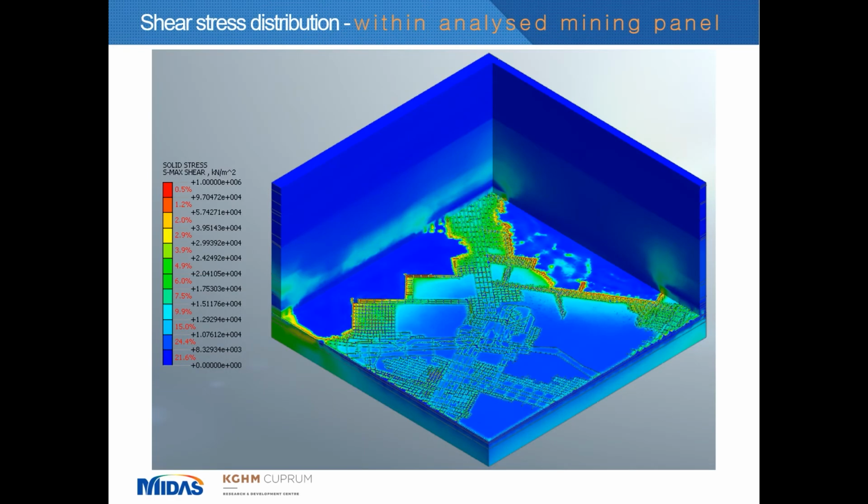And finally, the model which we have prepared within the part of the Baltic Sea Underground Innovation Network project included about 4.7 million finite elements. So it was a relatively large model, but GTS NX software does not have a problem with calculation of a model of such big size, as long as the mesh and model are well prepared and cleaned of any element that could badly affect the stability of the solution.